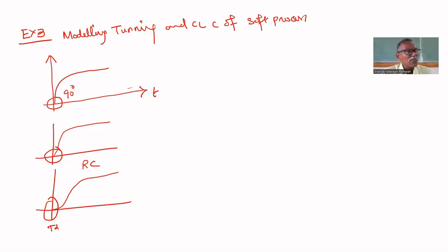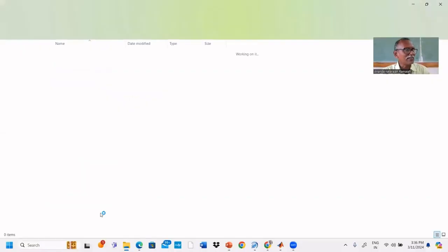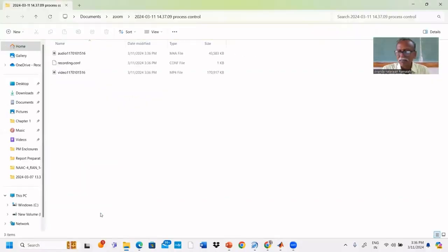All vehicles are first order, let us assume. If you are at the signal, some 4 or 5 vehicles are there before you, the signal changes, do all vehicles move simultaneously? No, you have to wait for some time. So as order increases, there will be delay in the response. Suppose the 4th vehicle, for that vehicle in that system, it is 4th order because 3 first order systems are cascaded, added to that.